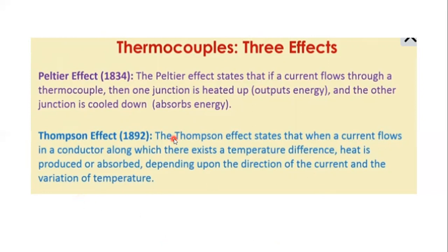Okay. So when we keep one junction of the thermocouple in a medium whose temperature is to be measured, there will be a change in voltage in that thermocouple, and that change in voltage is directly proportional to the temperature of the junction which is in physical contact with the medium. So that temperature can be directly converted to a voltage by using a thermocouple.